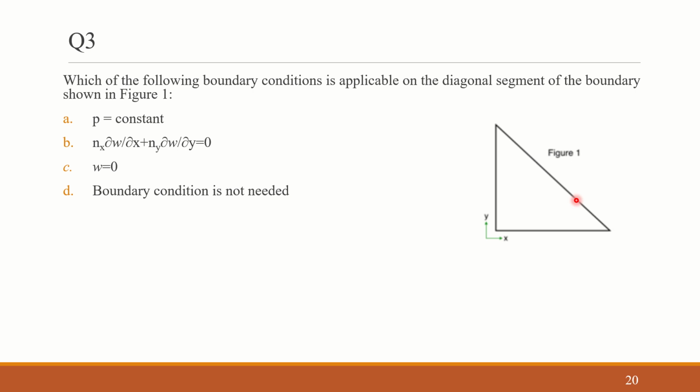We divide the system into smaller grids, and those grids will be much finer near the walls in most problems, because we use the no slip boundary condition and need finer, more accurate values. That is just for your information, not related to this problem.